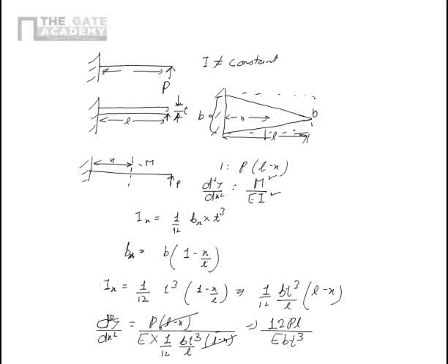So we reduce the beam weight or mass by 50% and the deflection increases by 50%. So there is a trade-off. The deflection increase results in a decrease in mass. So we have to get to a trade-off as to what kind of mass we want to save vis-a-vis what kind of deflection we can have.